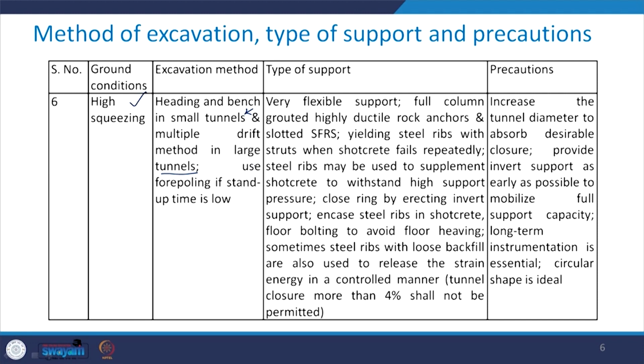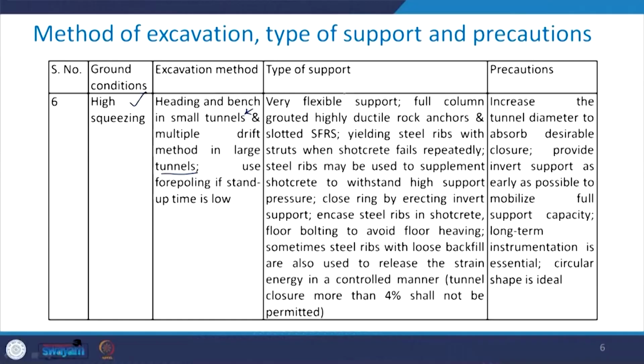Now the type of support, you can see that it's a long list. Let us see slowly what does this mean. In this case, one needs to go for very flexible support system. It can be full column grouted, highly ductile rock anchors and slotted SFRS.